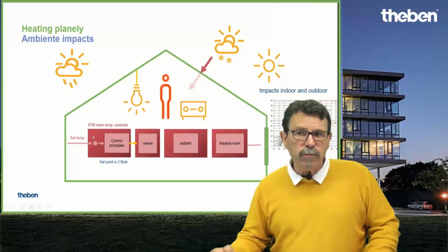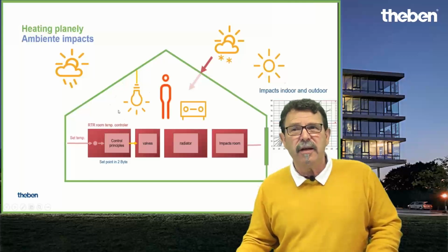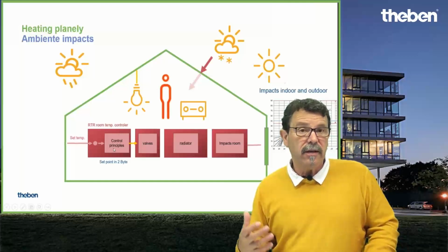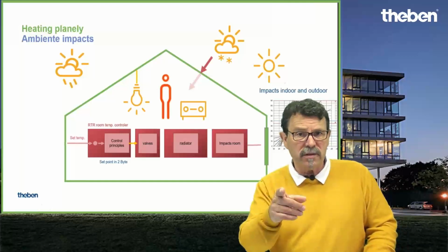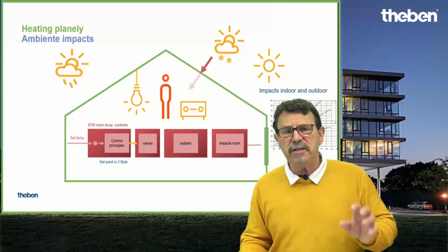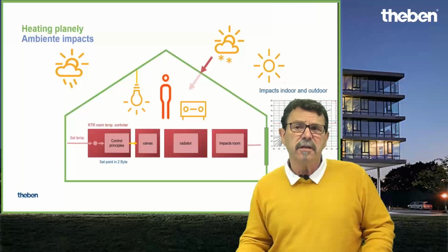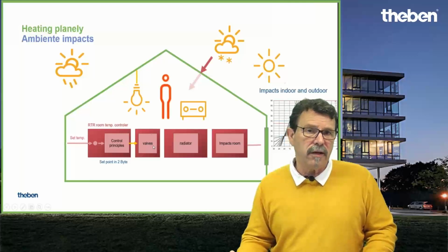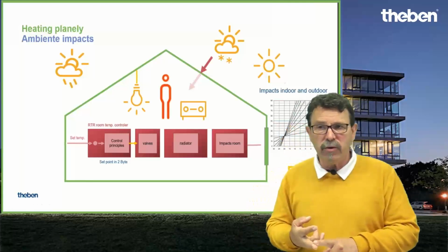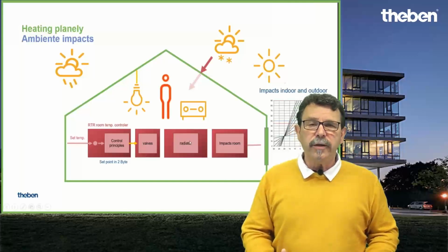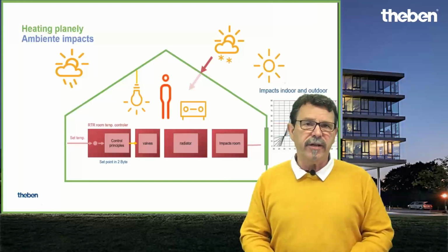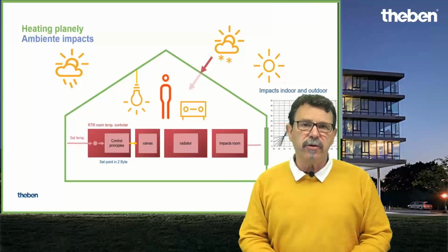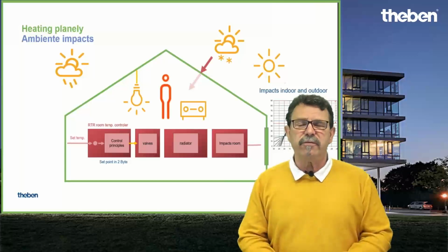Yeah, and so this room temperature controller is measuring every second how is the current situation inside of the building. It knows the set temperature, your desired temperature, which you adjust, which you preset, and the difference is calculated as a heating value, which is given to the valves. Again, either a motor-driven valve or a thermal valve, and then we open or we close, depending on the situation, a radiator: the flow forward, the warm water is coming in, flowing into a radiator or an underfloor heating, however, depends on the situation.